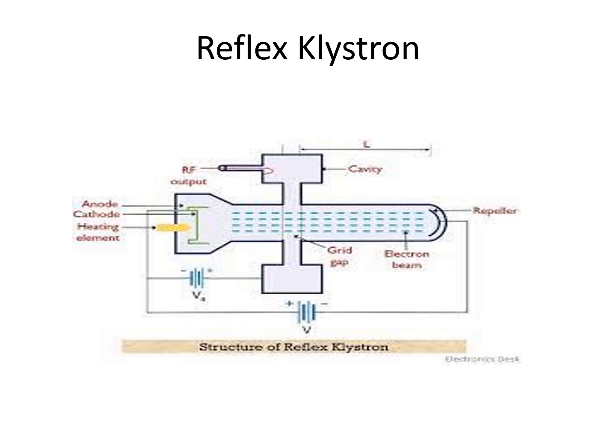The electrons will never reach the repeller because of the negative field and are returned back towards the gap. They repel back to the anode cavity due to high negative field. The electrons give more energy to the gap in their return journey and their oscillations are sustained.